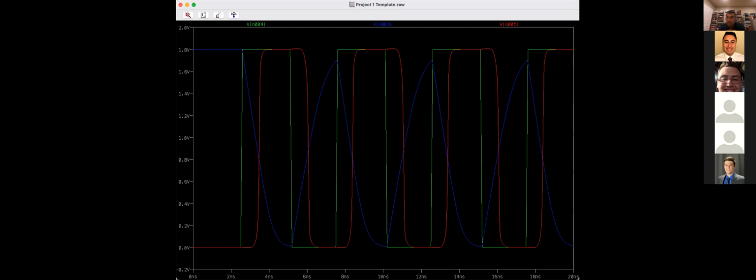Professor, I had another question. Go ahead. When we're considering our rise times and fall times, in this case the second inverter rise time, would we base that off of our input signal? Say we start our rise time as soon as the input signal goes high, or should we start it where we start to see it transition?